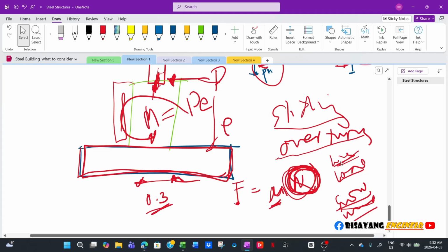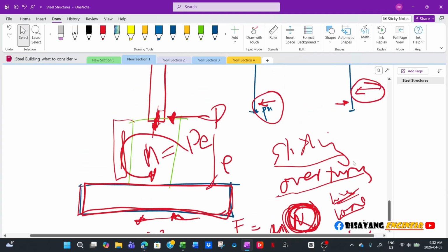It's common. We have hundreds of slab-on-grade buildings. Even the hotels I did in the US, those are 3-story, 4-story buildings, and the foundation is just at grade level, a thickened slab edge. I've personally designed more than 250 hotels in the US, and 90% of them were just slab-on-grade with thickened edge. Maybe in the Philippines it's not common, but it's common in North America. And then they say it fails and violates the NSCP. Well, that's according to you.